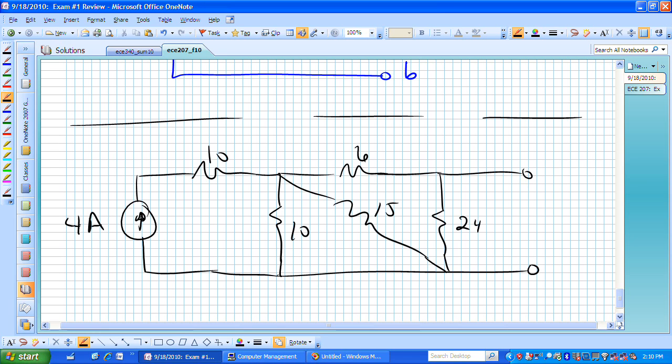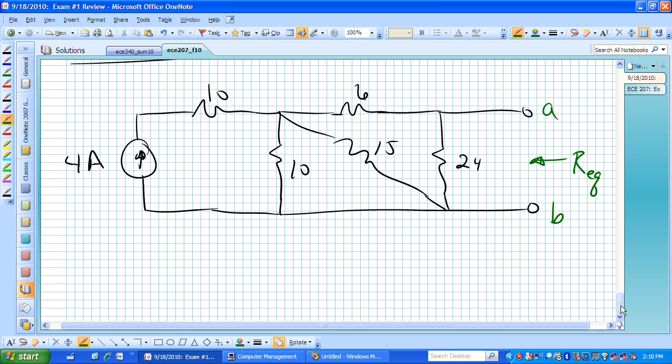If we want to zero our independent sources and try to find the resistance looking into those terminals A and B, that equivalent resistance would be our Thevenin equivalent. If we want to zero out a current source, then we look at its terminals, and the way that we zero out a current source is to actually remove it, or open up those nodes that are associated with the two ends of that current source. That's how we zero out an independent current source.